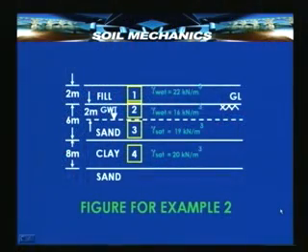Here is the succession of layers that I am talking about. In all, there are 4 layers. The first layer is the fill material of 2 meters thickness, which has been laid and compacted over the natural ground that is existing. Through borehole investigations, subsurface investigations, let us assume that it has already been established that the subsurface consists of a 6 meter layer of sand underlain by an 8 meter layer of clay, further underlain by a draining layer. We need to make assumptions like this from point of view of drainage.